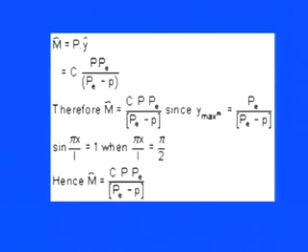So y maximum is nothing but equal to PE over PE minus P. And you see here sin of pi x by L is equal to 1 in the maximum loading condition, so we have pi x over L equal to pi by 2. So we have the real bending moment, in which the initial curvature is considered, as c P PE divided by PE minus P.